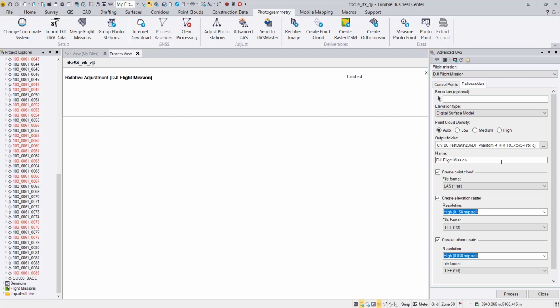Of course, including ground control points would help to give better accuracy. We would have less noise in the point cloud on the ground because the camera calibration would be done in a better quality with a higher reliability. And also with ground control points in general, we will have better absolute positioning accuracy relative to reference data, where we want to add the data to other projects. But for us, this is now our T02 processing with the DJI RTK Phantom 4 data.